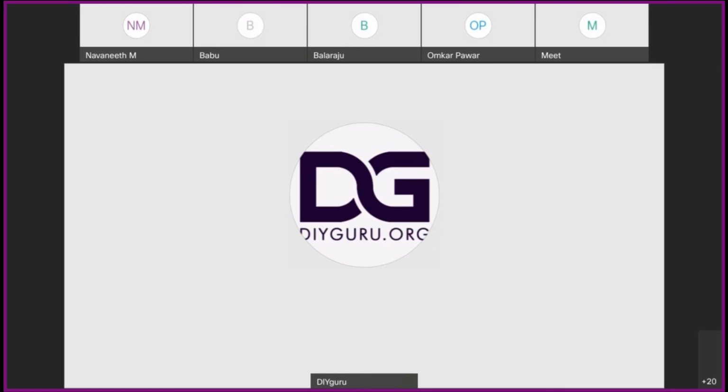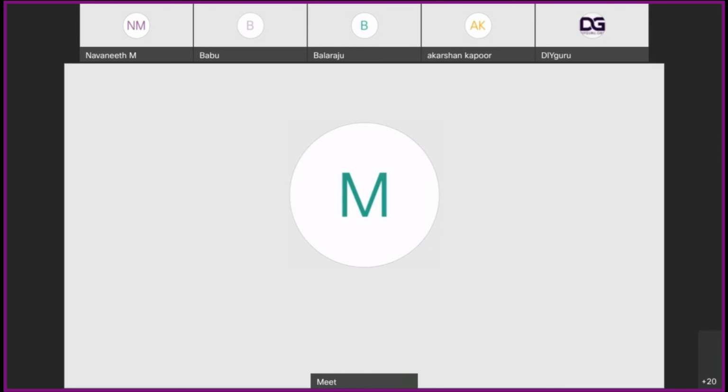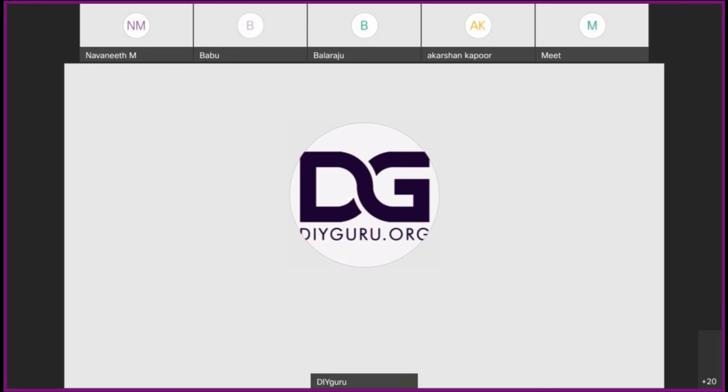Sir, in an actual battery pack, if we design a battery pack and want to simulate the whole pack with the cooling effect and all of that, how can we go for it? Then you have to go with ANSYS Fluent. You have to perform CFD, like if you're going with forced induction, that is a fan flow, or even natural flow.